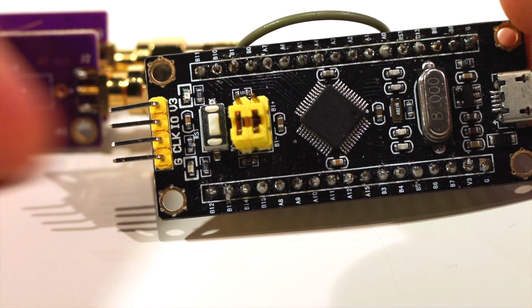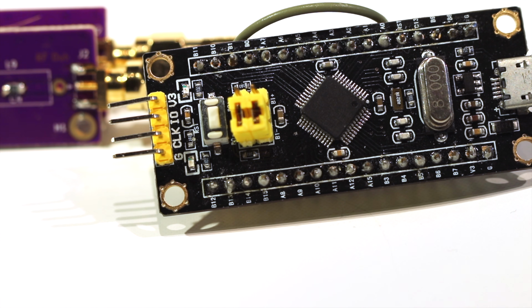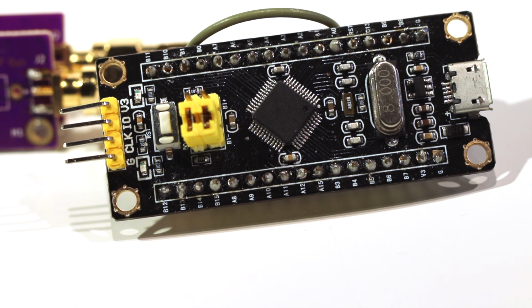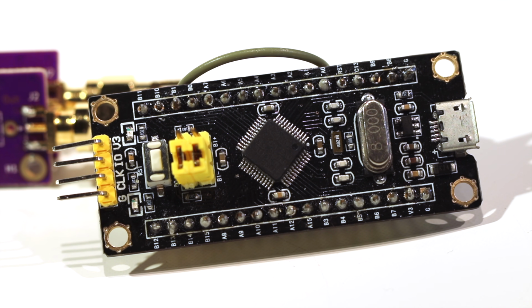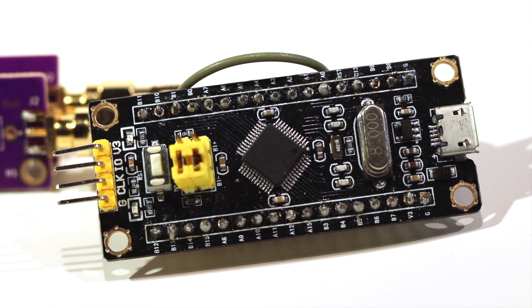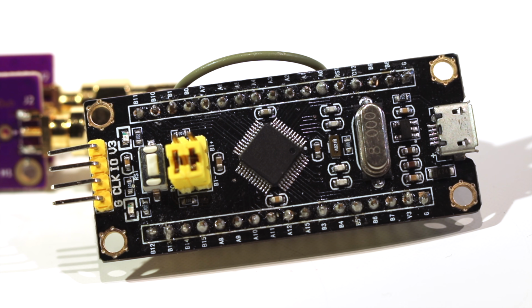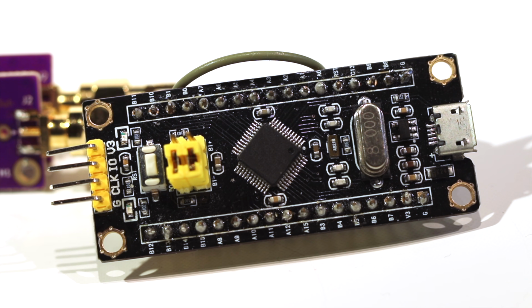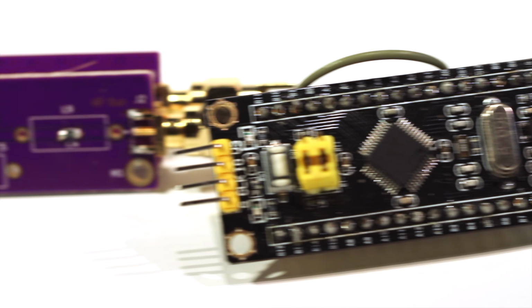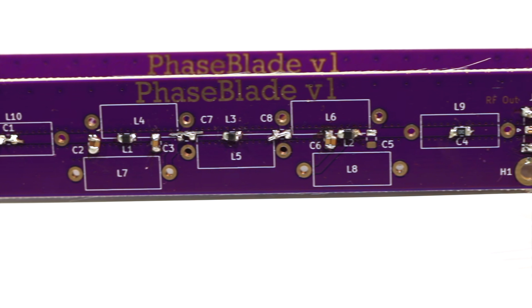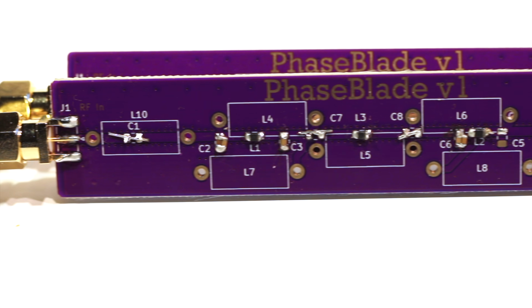And that's because I've had these blue pill dev boards, yes, I know this one's black, but that's what they're called, in the back of my closet for a few years, and for a few dollars, they're remarkably powerful. Coming in cheaper than ESP32s, and with a set of features extremely suited for this project, I thought I'd give it a go. Since the STM32 F103 on the board has USB, DMA and dual ADCs, it's almost like it was made for a task like this.